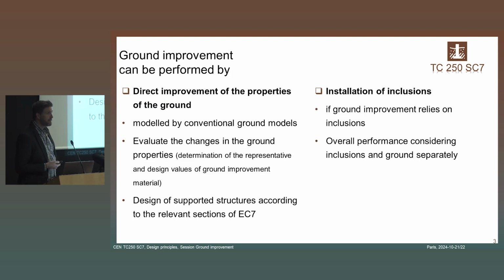We have two possibilities, actually, to reinforce, to improve the soil properties. We can directly improve the soil properties in itself without addition of non-rigid or rigid inclusions, and in this case we model the improved ground with a conventional ground model, but taking into account the fact that the soil properties have been improved by our execution process.